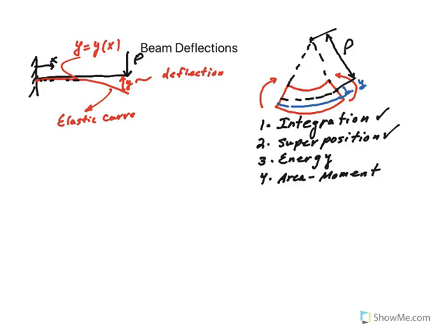You recall that earlier in the chapter, when we wanted to calculate the bending stress, we had the flexure formula, sigma equals My over I. Also, in order to derive this, we said that epsilon, the normal strain, is a function of the radius of curvature rho and y, the distance from the neutral axis to wherever you want to calculate epsilon.